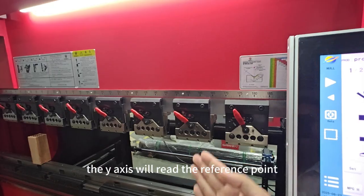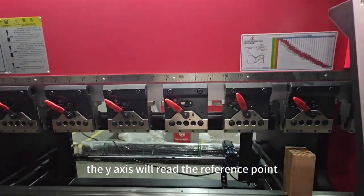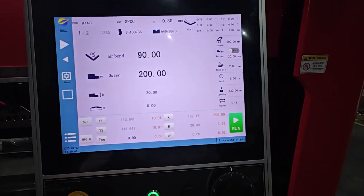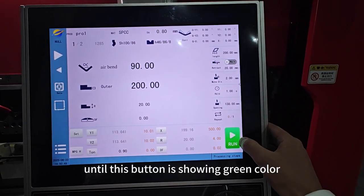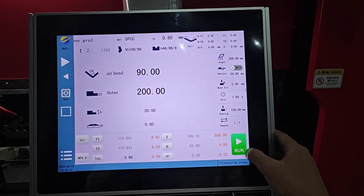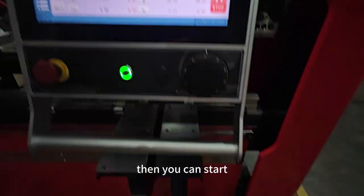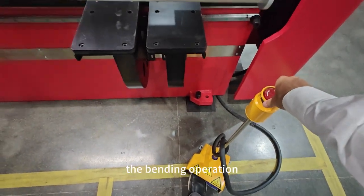The Y-axis will read the reference point. Also the X-axis will read the reference point until this button is showing green color. Run. Then you can start the bending operation.